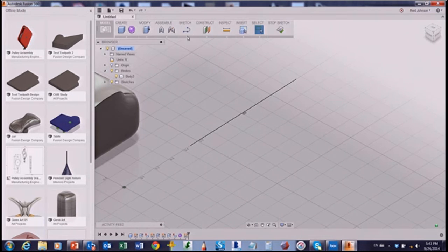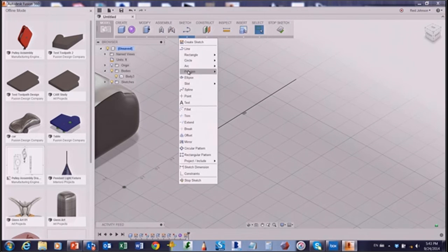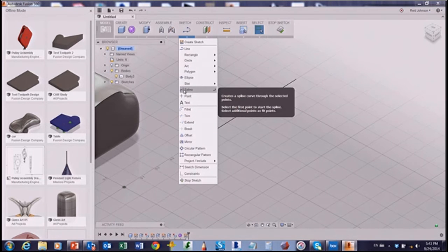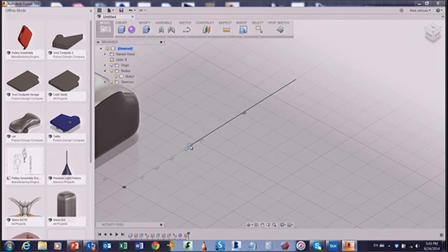If you come over to Sketch Line, the next one down, or a couple down, is called Spline. You can do splines in here. So I'll do a spline, and hover over that line you just drew. You can get a snap to the start point of that line. So I click once. I can click again, maybe do 3 points, and then back to where that line started.